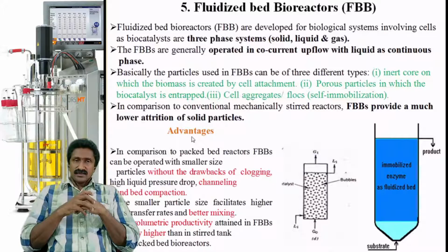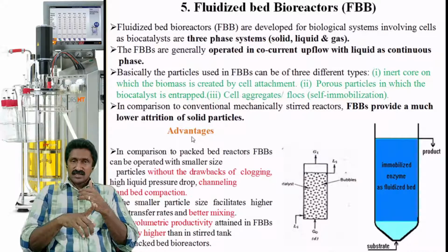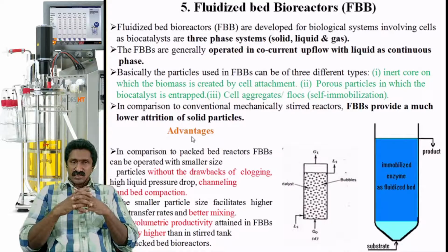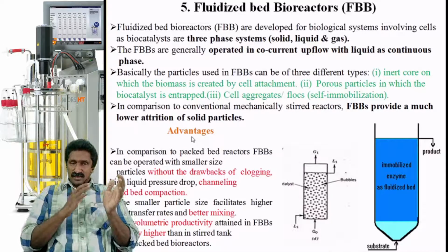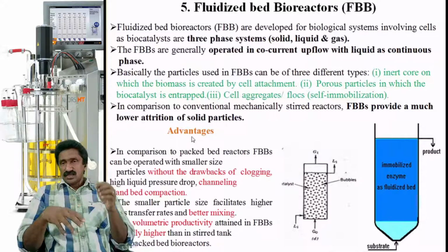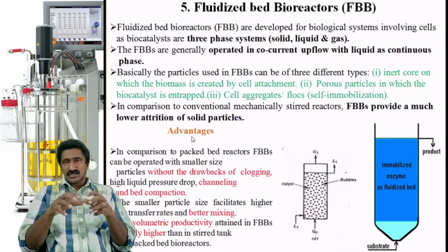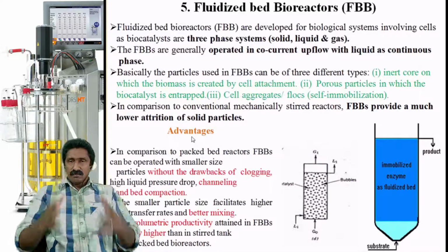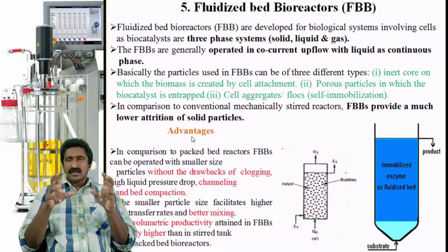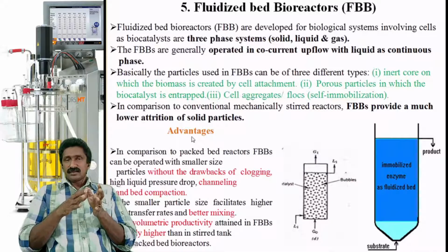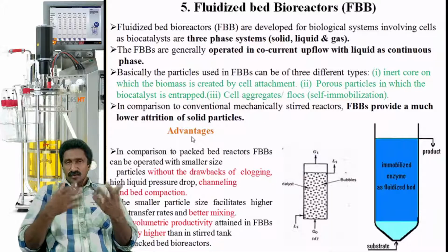Some advantages are there. In comparison to packed bed reactors, fluidized bed reactors can be operated with smaller size particles without the drawbacks of clogging, high liquid pressure drop, channeling and bed compaction. Usually, in the case of packed bed reactors, there is a possibility of channeling, clogging and blocking. All these things are possible in packed bed reactors, and that results in lower outputs.